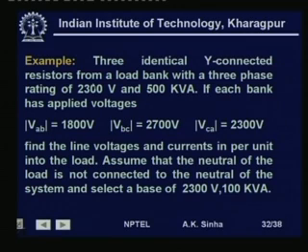So, the voltage base is the same as what we have chosen, but the kVA base for the load is 500 kVA, whereas our chosen base is 100 kVA. We could have chosen 500 as well, but this is just to illustrate how we can have different bases and we can convert them to per unit quantities for any given base MVA or voltage level.